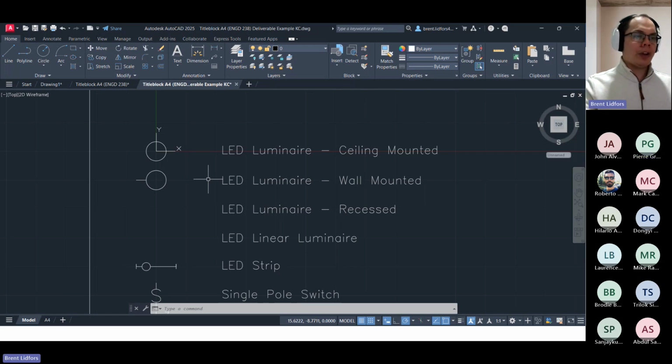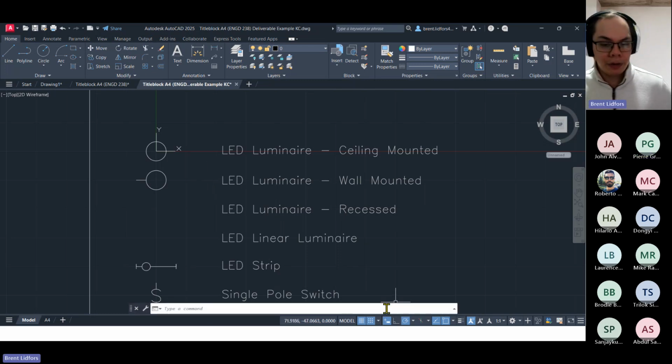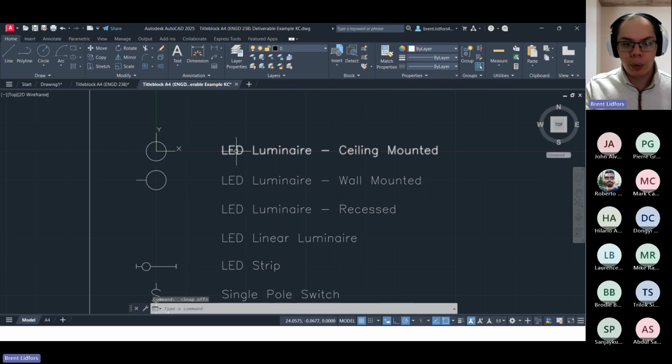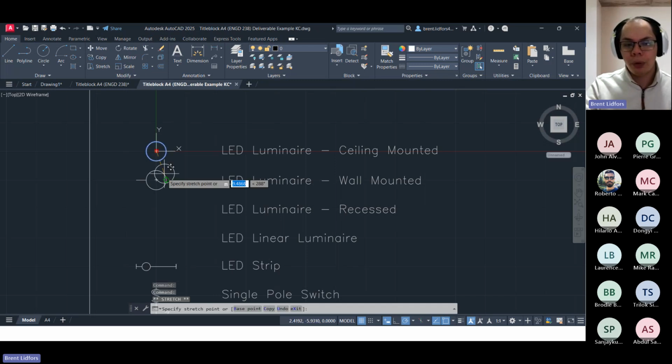Okay. That's kind of just a non-mentioned step, but yes, you will have to turn off grid snap in order to make that spacing 20, because obviously 20 isn't divisible by 9, like you said. So you're gonna have to turn off grid snap to make that spacing 20. The grid snap is just for making sure these symbols are all aligned and properly spaced.